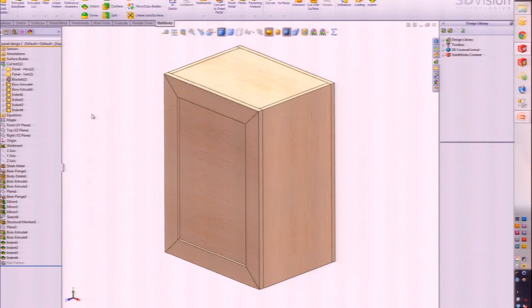So what we have here is a list of bodies, okay? The cut list, and notice that the solid body folder got renamed cut list. That's because a weldment feature is in there. So a cut list adds a little bit more functionality than just the solid bodies folder. What it does is it allows you to add properties to bodies just like we could add custom properties to part files. Okay? And I'm going to show you how to do that.